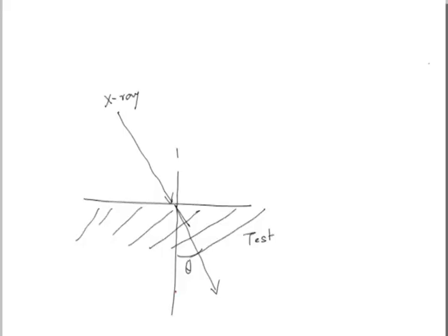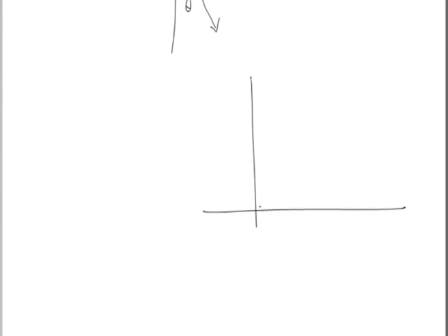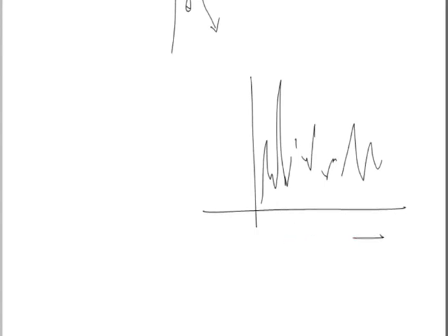That means this diffraction will be characteristic of the material or the crystal structure through which this incident X-ray is passing through, and therefore, we can get a signal like this. So, here, this is 2 theta and this is called intensity.